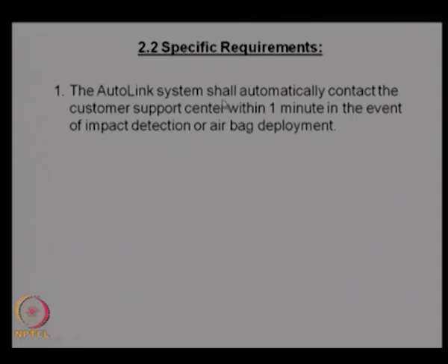So you can see that this is the first requirement. Again you can have additional requirements, like there should be a system to identify the impact, and there should be a time delay. So the system should identify an impact within a particular time. Similarly, the system should identify the airbag deployment and communicate this to the customer support center. So again additional requirements can be identified from here.